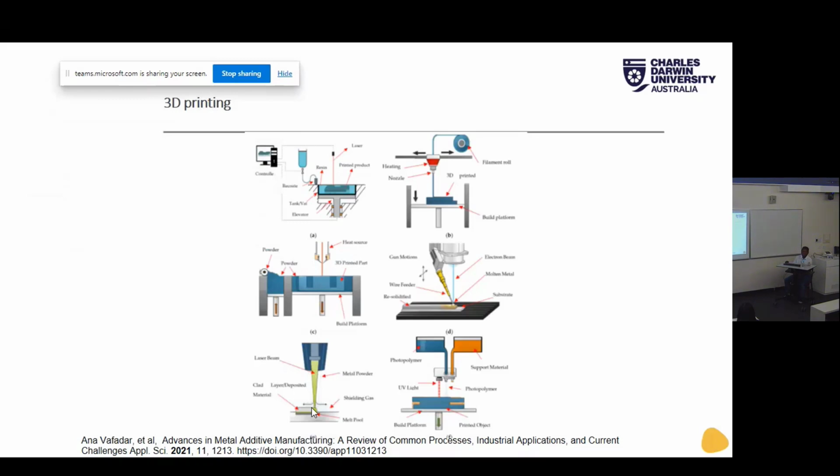Most of the prosthetics that are made are using selective laser melting. So they can be titanium, mostly titanium that is used, and sometimes magnesium and zinc are also used as metal powders to produce the form. For example, you can see here, one of this is again created by cold spray printing, and Matt has actually done that. I'll show you a video now in which Matt is actually displaying his capabilities as one who produces this part.